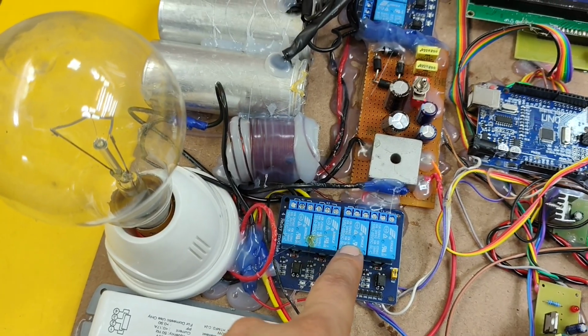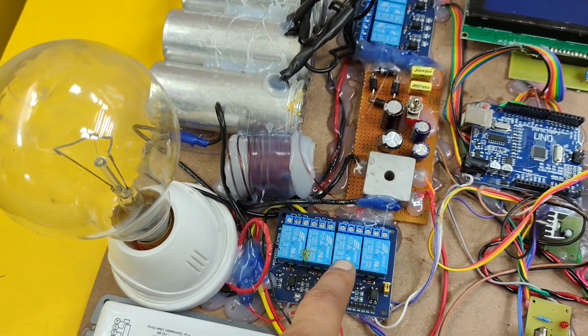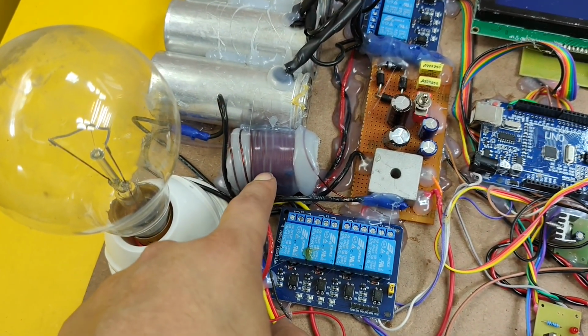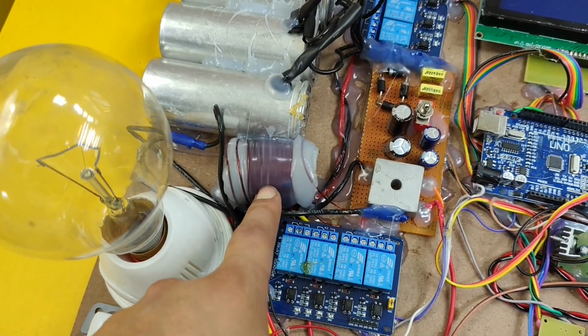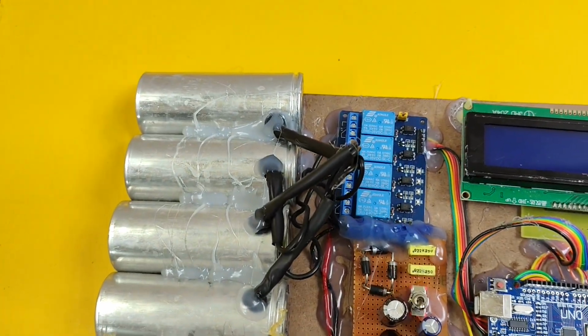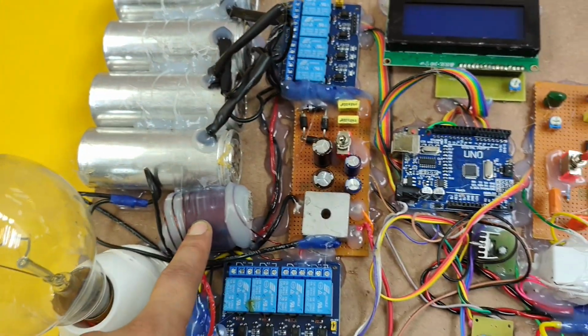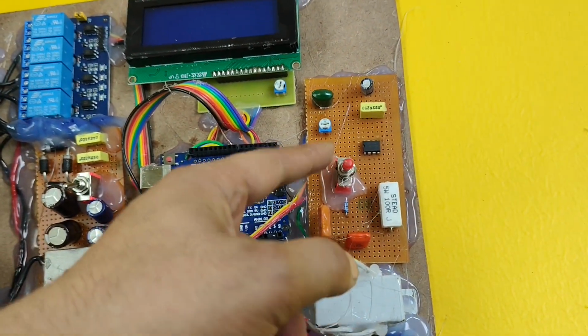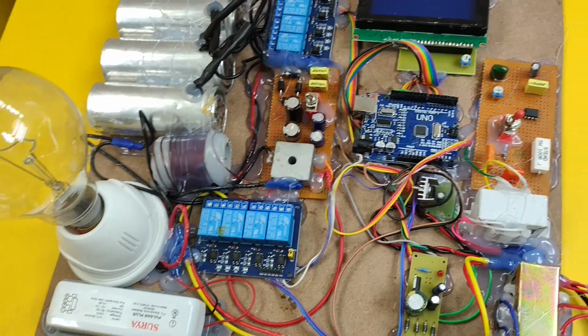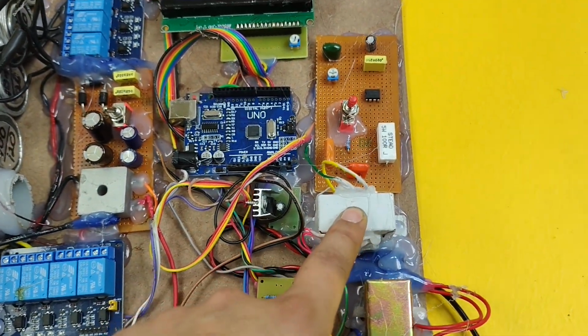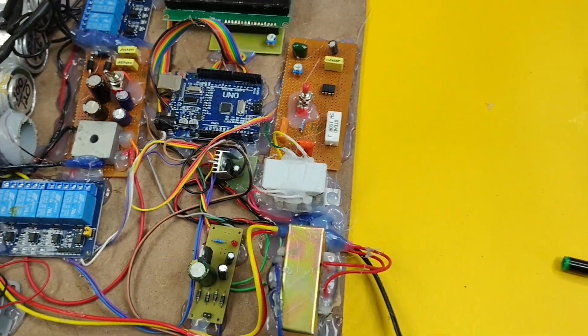Now this third relay over here is used to control this inductor filter. So if this inductor filter is added, then total harmonic distortion or THD will be improved, right? And these 4 capacitor banks will improve the power factor as well, and THD as well. And this is the hardware selection button. This is toggle 1, this is toggle 2. Toggle 1 is for selection of inductive load and capacitive load, right? And this is the current transformer which is used for the zero sensing circuit, right?